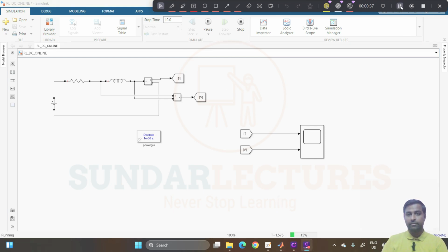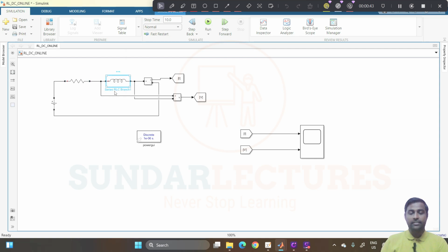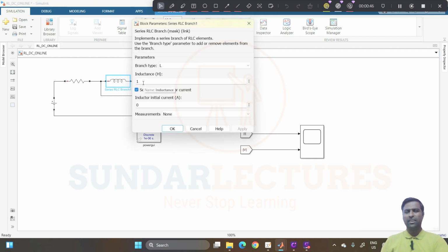Wait till then. One thing before that, change this R value to 2.5 and this L value to 1 Henry. Maybe the graph will be very clear to understand, so that is why I have changed this. You yourself change the R and L values, calculate manually with pen and paper, and try to compare that with MATLAB. But for explaining things, I have changed the R value to 2.5 and the L value to 1 Henry.